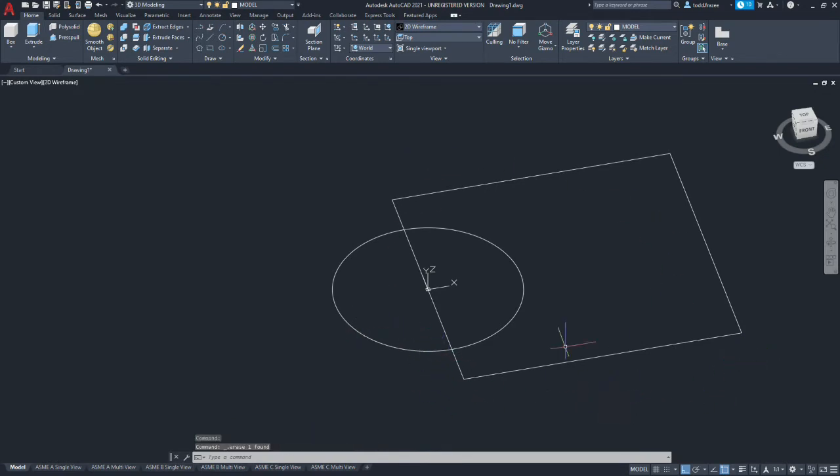Alright, so now we want to do a move. But before we do that, because we did individual line segments, the loft command needs it as one continuous piece. So we do that by the join command. Join. And we select the entities we want to join together, which are the 4 individual line segments. And then we hit enter, and now we should be able to select on it as one square. So when you actually use the rectangle tool, it's automatically doing that step for you.